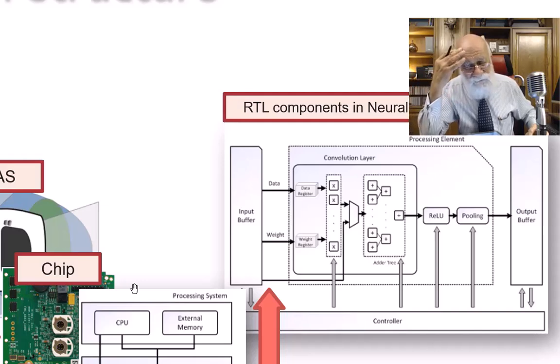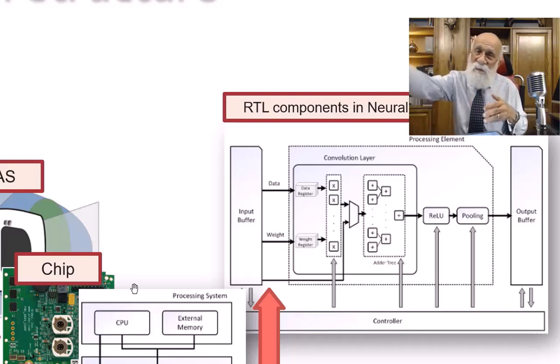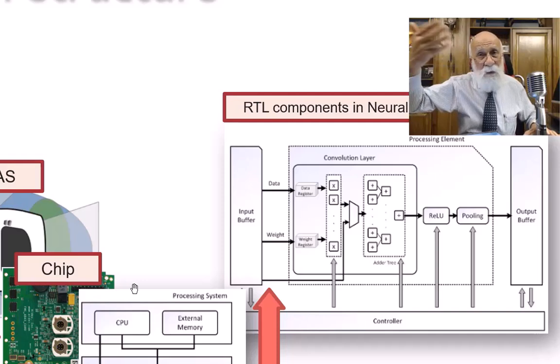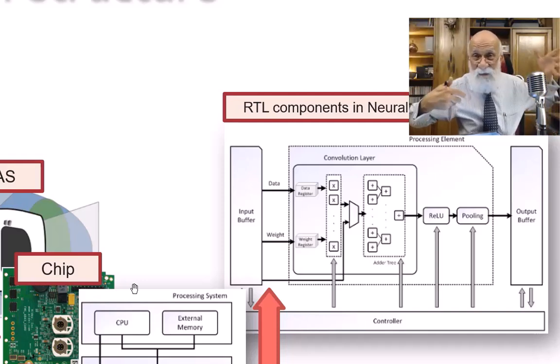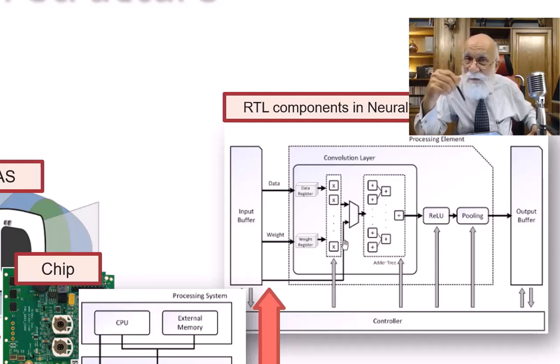So instead of saying that I have a filter, I say, well, yeah, there's a filter there. But then how is this filtering done? Filtering is done by multiplying something by something, subtracting something from something, multiplying an array of a filter by an array of an image. All of these components become multipliers and adders and subtractors and things like that.